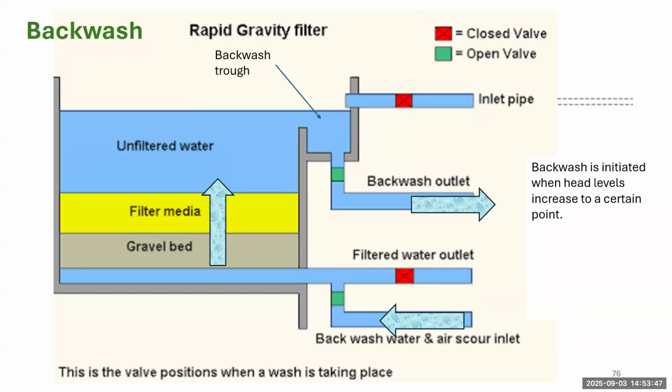A couple things to think about here. In a gravity filter, the backwash is usually initiated when the head level increases to a certain point, and what we're talking about there is the water that's above the filter when it's filtering.